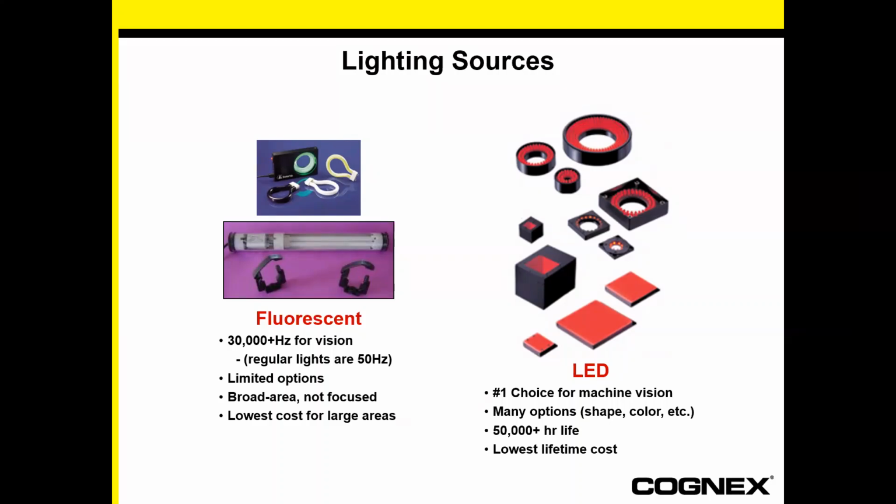I've got lots of rules of thumb for those of you who have done my full training courses. You know, if it's a square part, I generally might use a square light source. If it's a round part, could be a round light source. Every light source has its particular pattern that it puts out. And then these lights can also be angled to give us greater contrast.